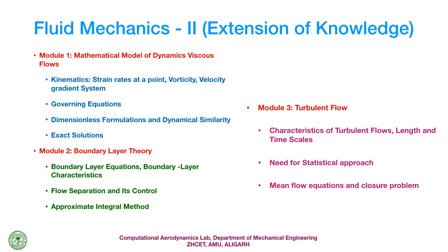As you might know, on a flat plate which is 0.1 meters long, with air flowing on it at a velocity of 2 meters per second, it will give you a smallest length scale of around 0.01 mm, and the largest length scale will be of 40 mm. So you can see that such a large amount of length scales are involved in this flow.